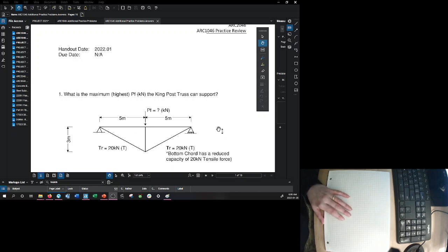We know that if we take this and draw the free body diagram, which makes sure it's stable, and sum the forces in the y, x, and spinning, or the moment about z, we can figure out what it takes for this to be stable. We also know that we can cut any section of it. If the whole is stable, any component of it must not be sliding up and down, sliding back and forth, or spinning in space. That was called method of sections. We know we can then use method of sections to solve for internal forces.